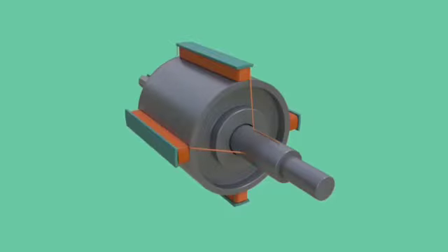DC current is supplied to rotor via a pair of slip rings. This is the reason why rotating magnetic field approach is used in alternator. If rotating coil method were used, slip rings would have to be fitted along with the armature coils in order to collect electricity.